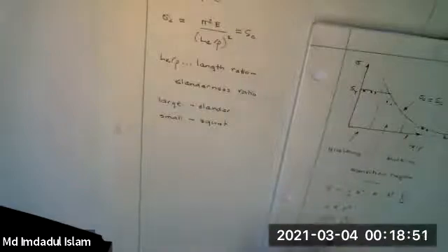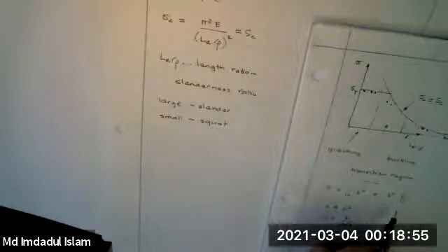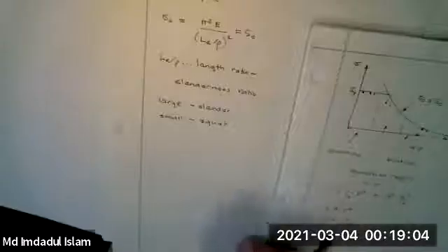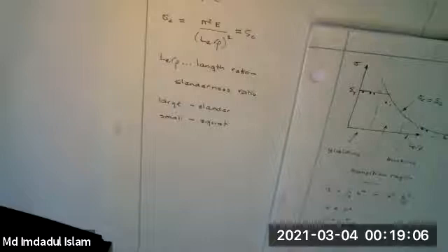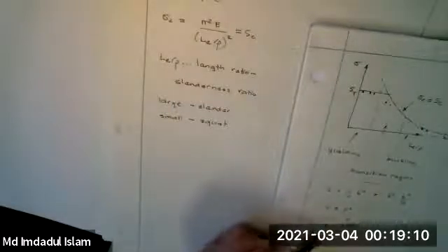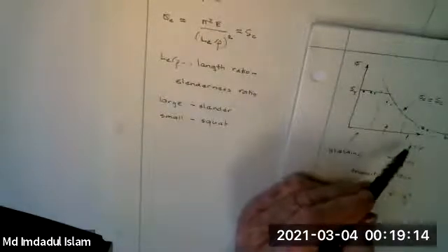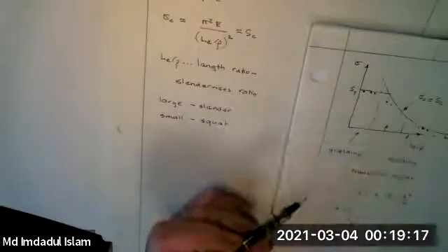So that's what you would use for a square. And if you had a rectangular one, then you do the half BH and you get a similar result. So you can always get this radius of gyration. Go look up the second moment of the area, divide by the area and take the square root, and you get the radius of gyration. Then, depending on the end conditions, you can get this length, and so you can always get this for any shape.